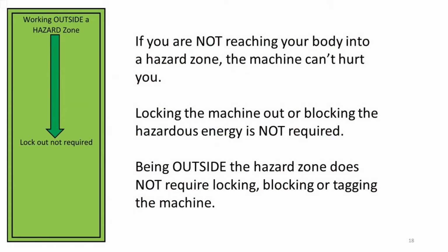If you are not reaching your body into a hazard zone, the machine can't hurt you. Locking the machine out or blocking the hazardous energy is not required. Being outside the hazard zone does not require locking, blocking, or tagging the machine.